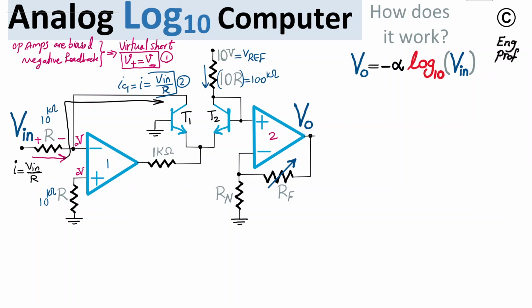Let's find this IC2, because this current that is going through the resistor 10R effectively becomes mainly the current of the collector, and of course the current of the emitter. For both transistors T1 and T2, we make the assumption that beta, the current gain of the transistor, IC over IB, is pretty large, much larger than 1.